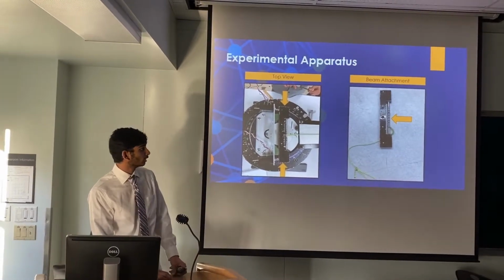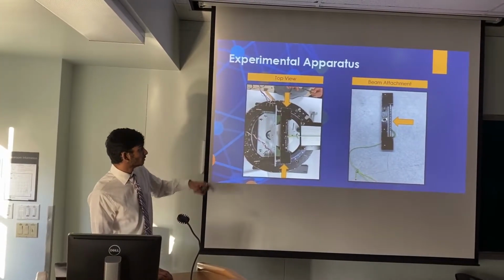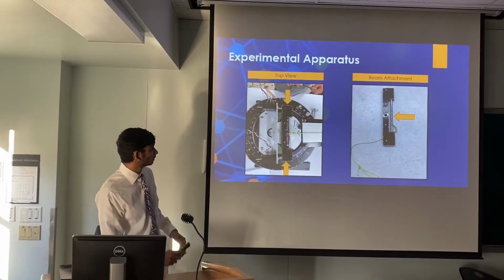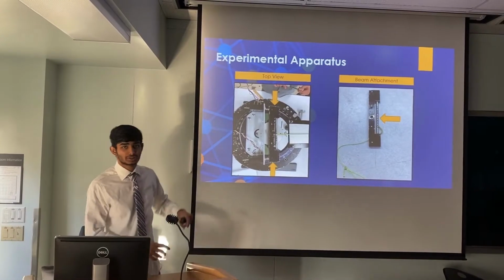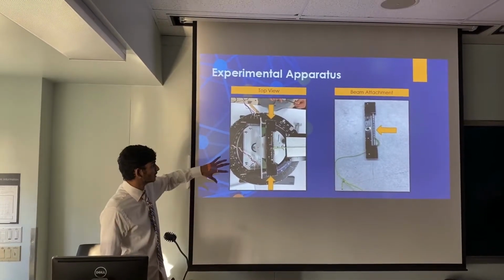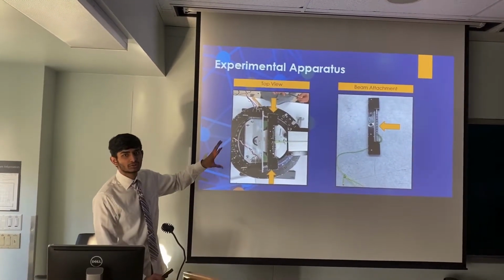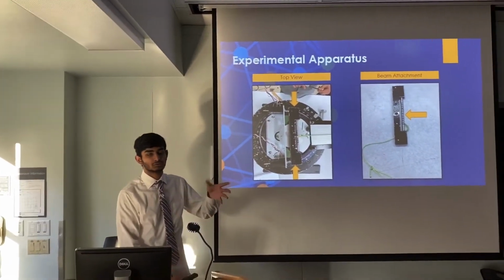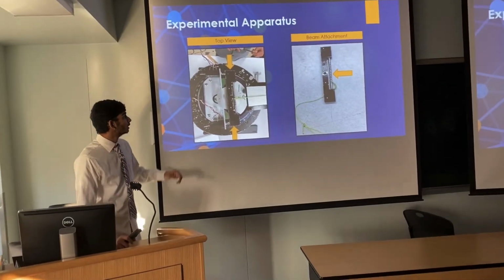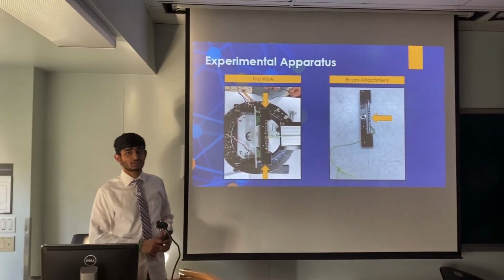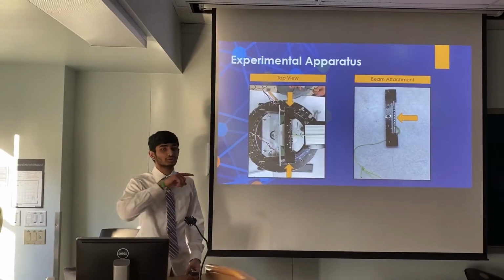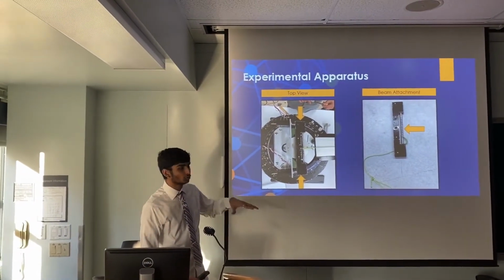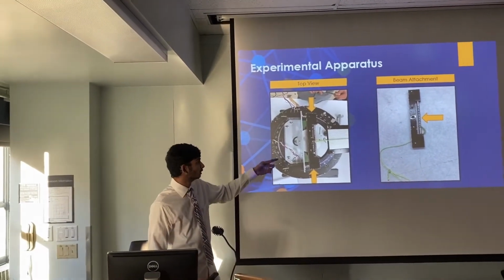In this slide, we have a close look at the top view and a picture of the notch bar. In the close look, as you can see, we have two linear potentiometers fixed with the mount, and we have a rotating disc, so we can move this apparatus to 0 degrees and 90 degrees for various load application locations. The notch bar is attached to the free end of the cantilever beam, so we can apply load at various locations of the cross section of the beam.